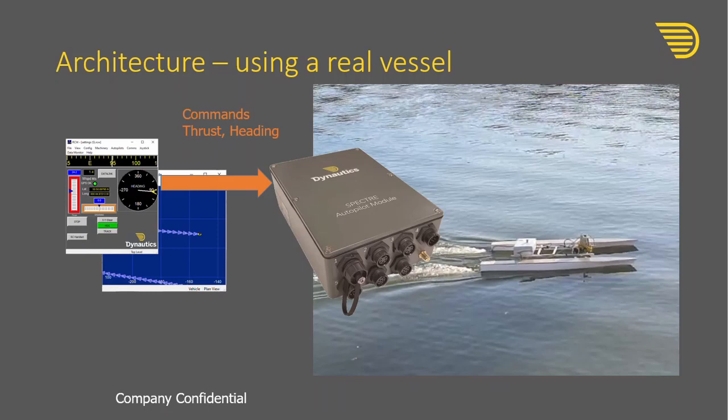Using a real vessel, it's very much the same sort of idea. You have an operator workstation, you send commands to an autopilot that then does the rapid thinking and following headings and so on, but you give commands to the vessel. But the other part of it, which is just as important, is that you've got to get data out of the autopilot to come back to you to give you situational awareness. Without that, you're driving blind.